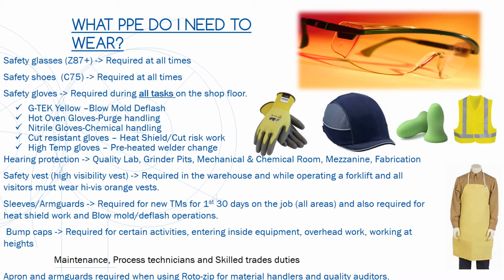The G-TEK yellow are used for blow mold deflash. Hot oven gloves for purge handling. Nitrile gloves for chemical handling. Cut resistant gloves for heat shield and cut risk work. And high temp gloves for preheated welder change.